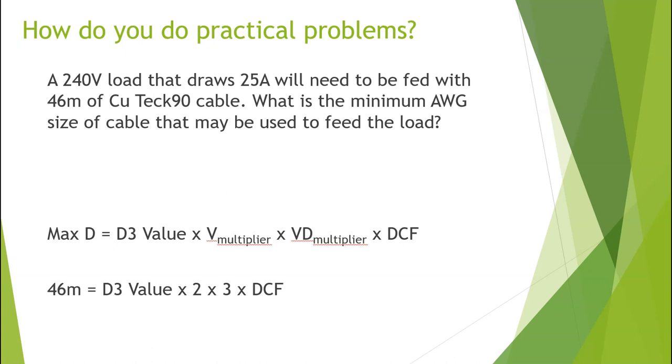So here what we have to do is put the data into our base calculation that we looked at the beginning of this video. Our base calculation for a voltage drop problem is focused on calculating a maximum distance that we can run. In our case now, where we're looking at it from the real world perspective, a more practical example, we already have the maximum distance.